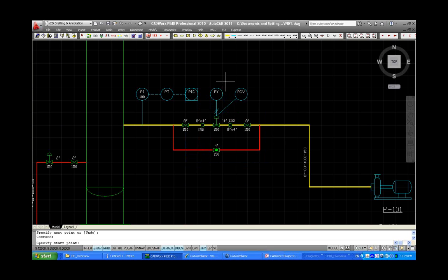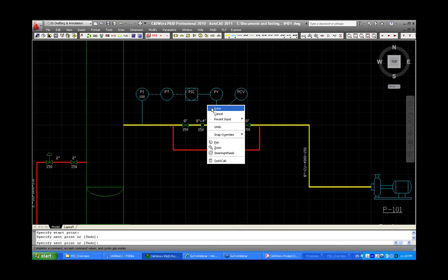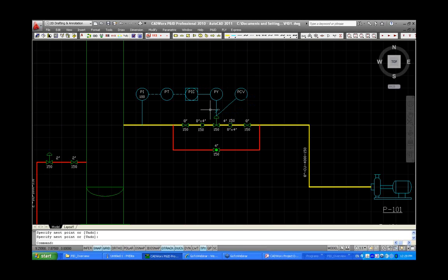So okay, we're almost done here. To finish this loop, I need to add another instrument line. So these lines that we're drawing in, this pneumatic line, the electrical lines, instrumentation, and the instrument lines are all available here. So we can always go back here and select the lines that we want and finish these instruments off if we need to. So I'm going to draw an instrument line from this symbol to this symbol, and now I finished my instrument.